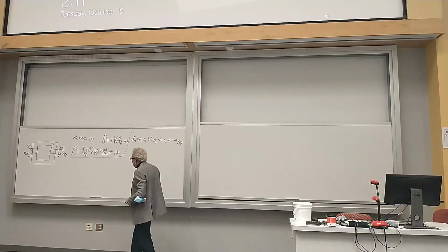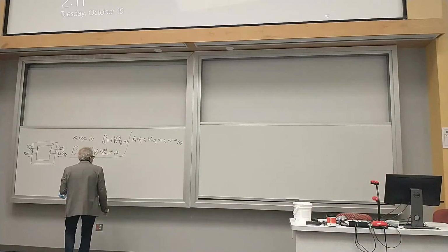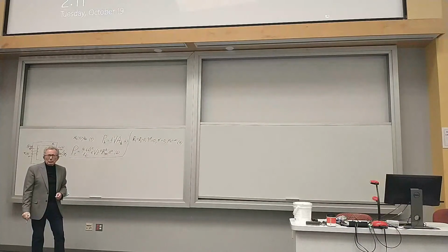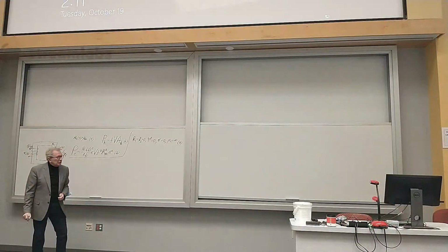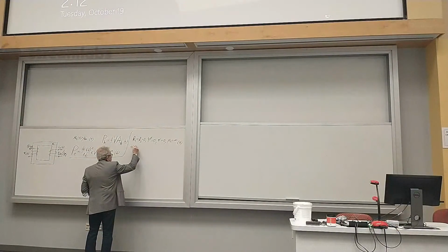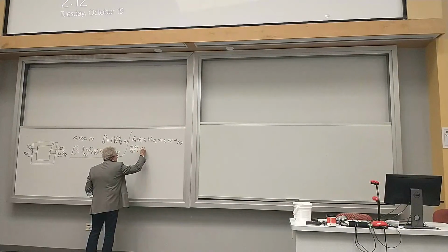So under this condition, I derived the following terminal relations between the primary and secondary voltage and primary and secondary current. Namely, I derived that the ratio of the primary voltage to the secondary voltage at any instant of time is equal to the turn ratio.